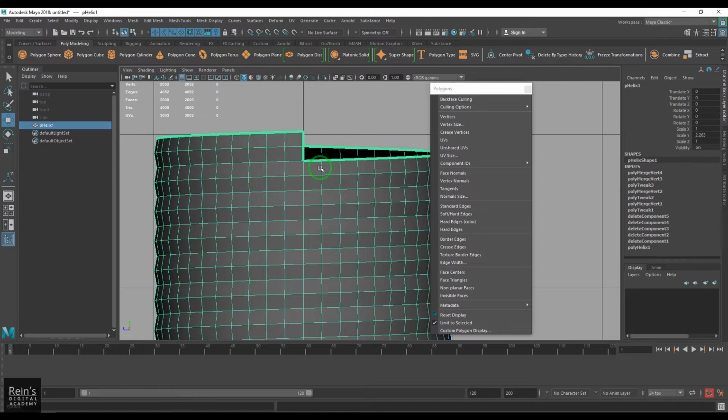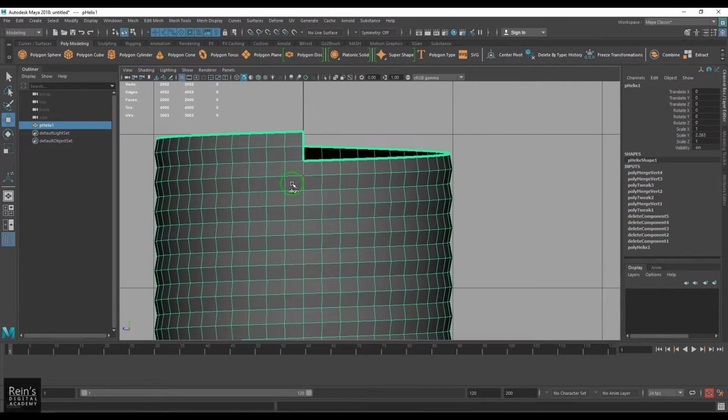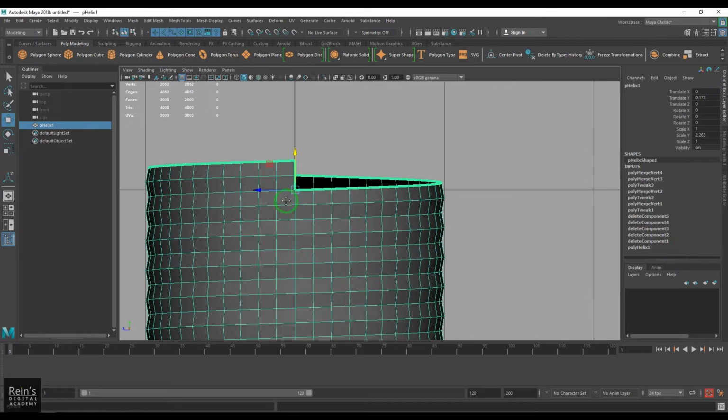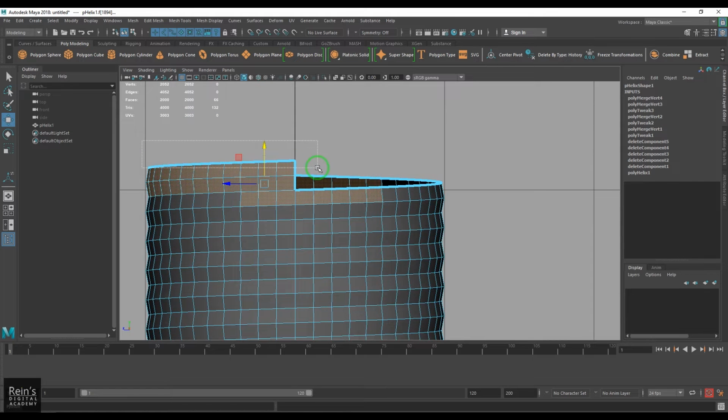Okay, I just want them to be equal. That's what I'm going to try here. So firstly, I'm going to set the pivot point to this point, and then use the grid snap, and then snap it there, and delete all the faces which are above that grid.